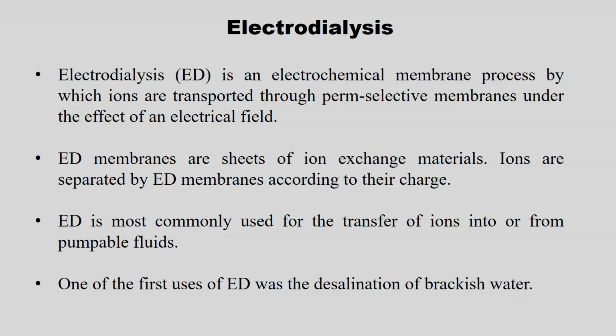But remember, the monovalent ions are partially removed using nanofiltration, but completely removed using reverse osmosis. So, based on your application you have to choose. Though nanofiltration shows some advantages over reverse osmosis, we are supposed to choose the membrane process based on the process we are going to apply.